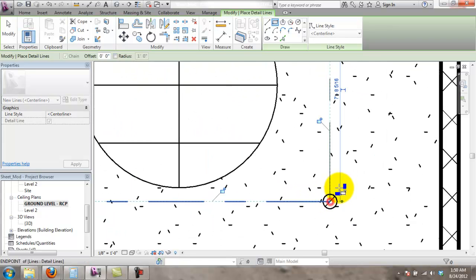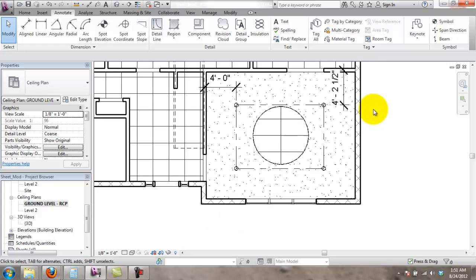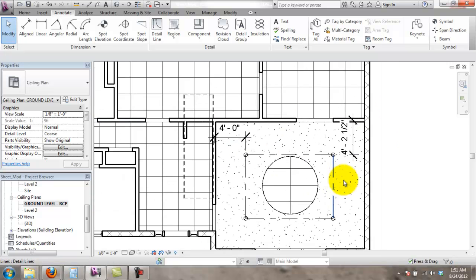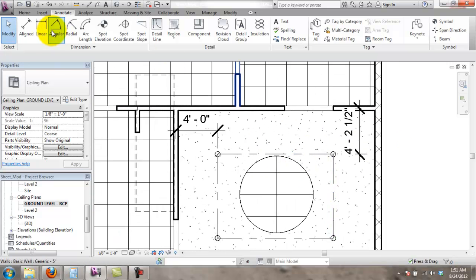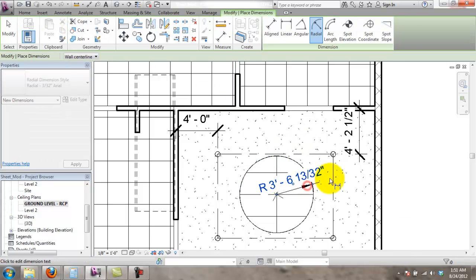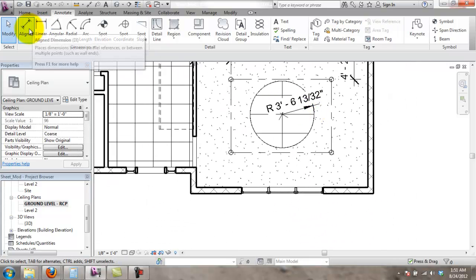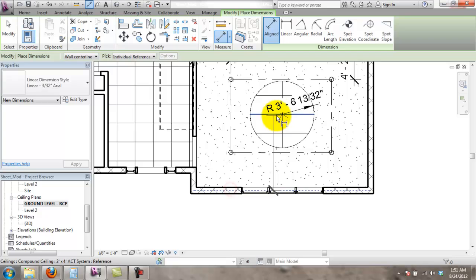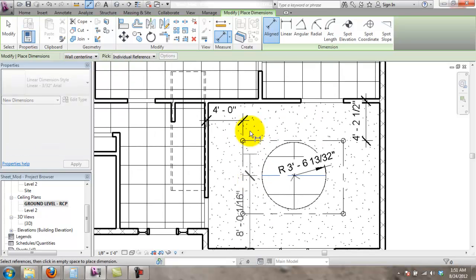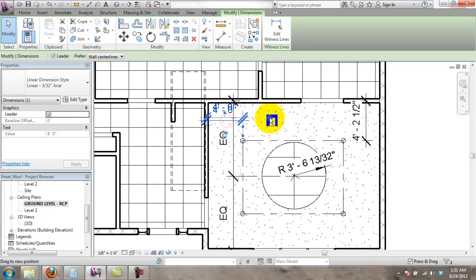Okay, and that says that these guys are all in as a line, so all you need to do is provide 2 dimensions there. And you would specify a radius here, and with every radius you need a center point. However, we use the equals, so maybe to the center of this thing you have this, and it looks like it actually moved on me, but I want it to be equal, so I'll change it.